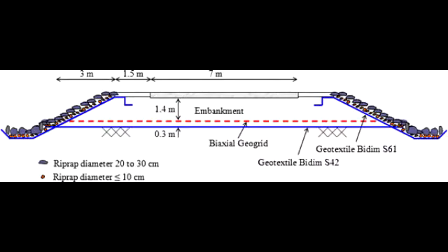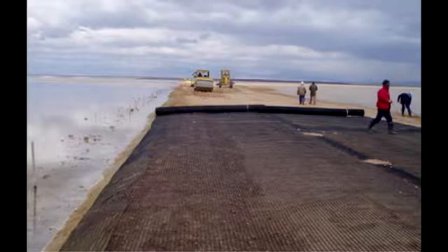From the results, it shows that the bearing capacity of the weak subgrade was improved when using the geosynthetics in reinforcement for unpaved road. Based on the data analysis, the effect of geosynthetic on the improvement of bearing capacity for the reinforced increased compared to the unreinforced result. When the bearing capacity was improved, the value of undrained cohesion also increased and it becomes negligible for the subgrade. Thus, the subgrade can resist the applied loads.